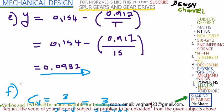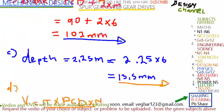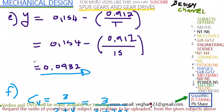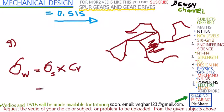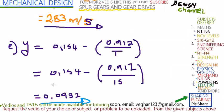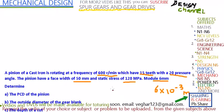So how do you calculate the working stress? Because here we have already calculated the velocity factor. So the working stress is the velocity factor multiplied by the static stress, because it moves at this velocity. This is a basic stress or static stress, whatever you call it.